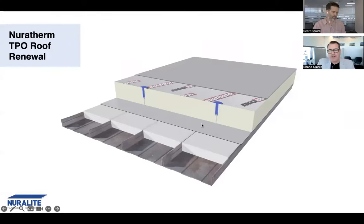We then installed our flat PIR board, and I think Palmerston North Hospital was 100mm PIR board, which gave them a continuous R value of 4.5 across the whole roof, which is thermally mechanically fixed. Does that make sense? Mechanically fixed with thermal fasteners into the roof, and then finished with that single ply thermoplastic TPO membrane. Just a quick build up there of what we did.